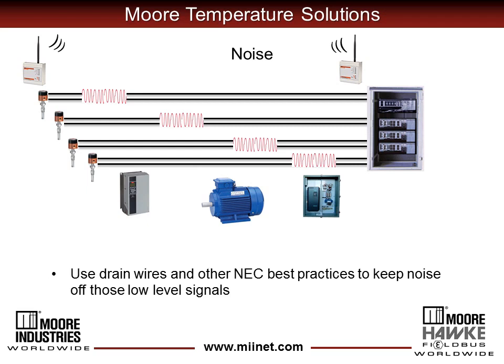So I encourage you, when you're direct wiring signals, to be sure that you're using best practices to keep noise off those wires. That means drain wires, conduit, proper grounding, physical separation, anything at your means.